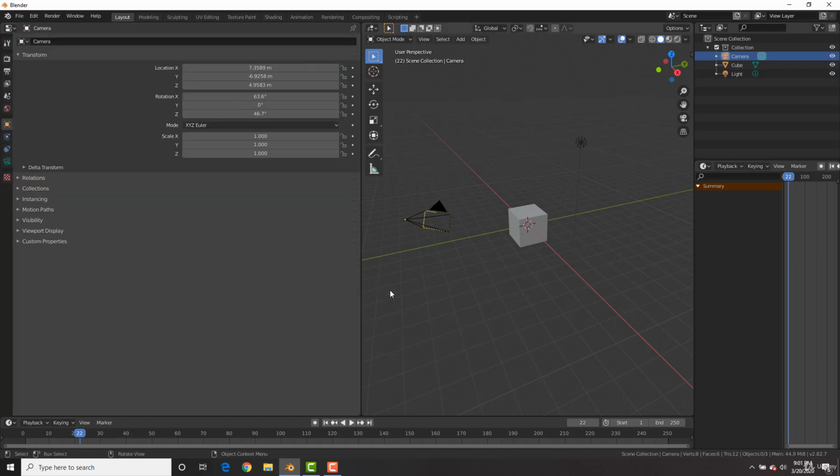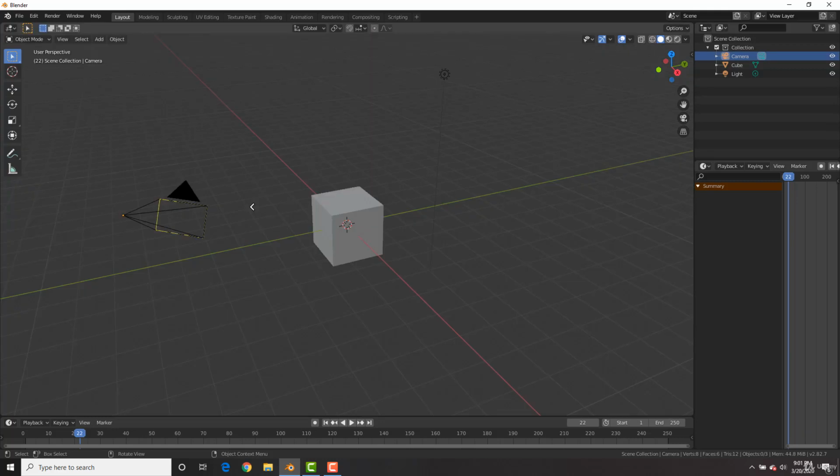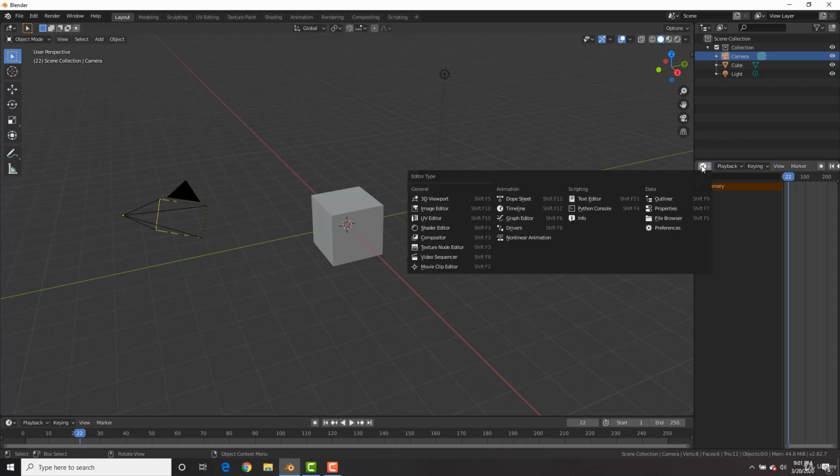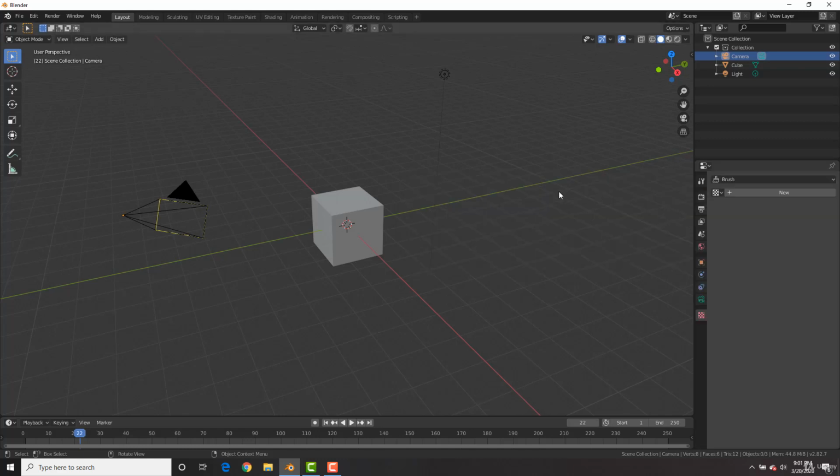And then to merge windows, all you have to do is go to the crosshair on one of them. And if you left click and drag to the left, it will collapse it this way. And without letting go of your mouse, you could go to the right. And if you wanted to collapse that way, you can't. So you could decide which way it collapses and then just let go of your mouse, and boom. We have the 3D view back in style. All right, let's change this back to the Properties window, and there we go.